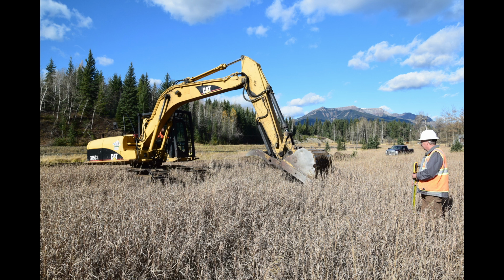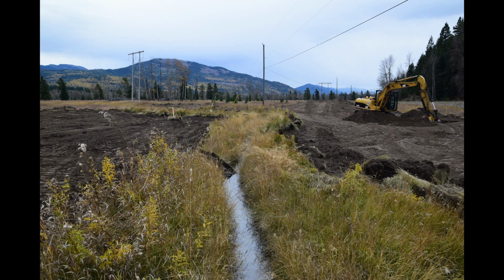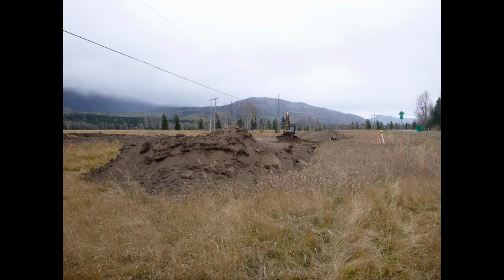The day of construction, I dug a deep test hole in one of the planned wetlands and found that silt overlaid rock and gravel, and there was no groundwater in the gravel. In excavating basins for the wetlands, we would cut through the silt and expose the dry gravel beneath. We agreed to use the compacted clay liner technique to build the wetlands, only using the silt texture soil because there is no clay in the meadow.